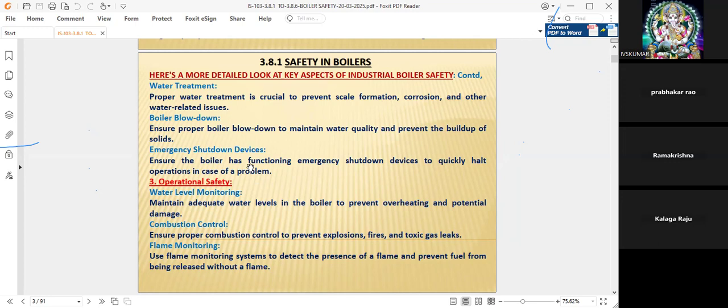If any emergency shutdown comes, we have to immediately see that the boiler is kept in manual, not in auto mode control, and the gauge glass and other things will be taken into manual while attending to the emergency shutdown, and thereby the next connected system. The emergency shutdown will come, but during that time all device functions must be perfect. Otherwise, it will be operated manually for some time, controlling the gauge glass level. Gauge glass level means steam drum level.